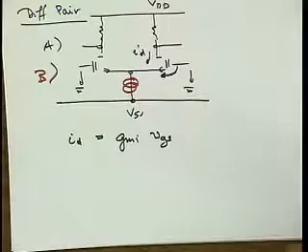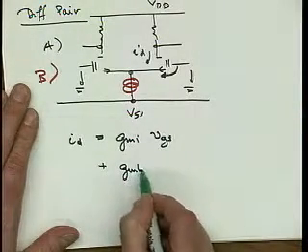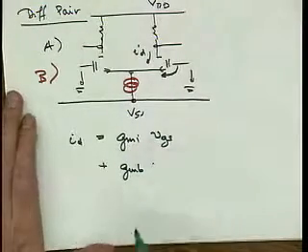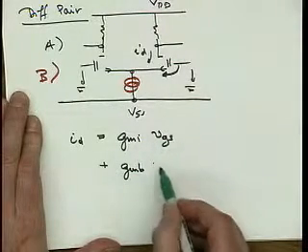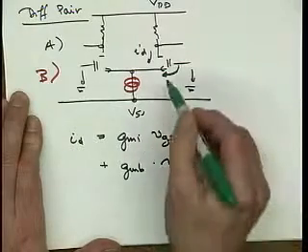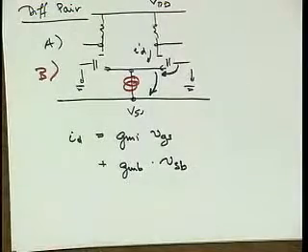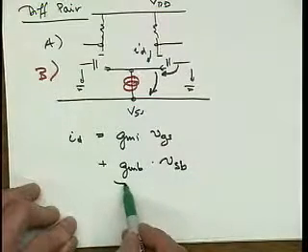But then there is also another transconductor in here, right? The body transconductor, and its current doesn't depend on VGS, but it depends on VSB. So here suddenly it's this voltage. How I change this voltage determines how much extra current is flowing due to this term.